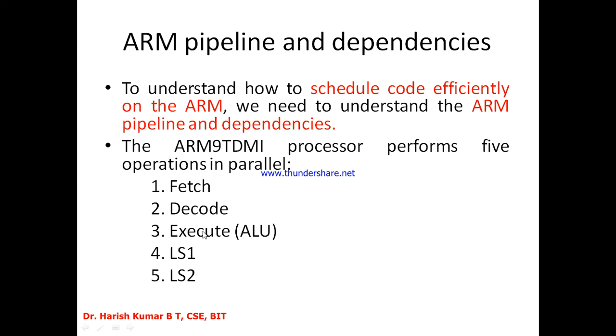Here the address is computed, here the data is read, and say it is LDRB. For LDRB, the address is computed here, and that byte is read from the memory in this stage. After reading that byte, while loading it into the register, what load ultimately does is write to the register. What is read here is a byte, but when that byte is being written to the register, it gets sign extended to 32 bits. That is what is happening here.